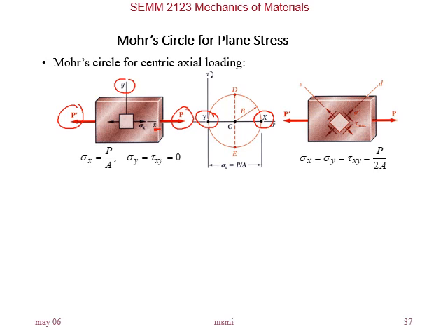Any other point on the circle represents the stress condition on a plane in a certain direction. So if you say I have this point here, you draw a line to that point. That line represents the direction of the plane from the reference. So if x is the reference, it goes clockwise, right, to theta. And the coordinate here is the stress.